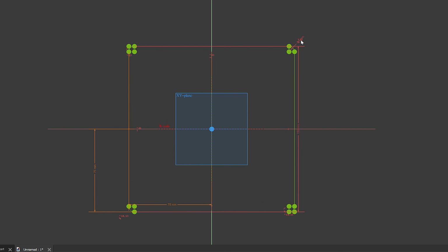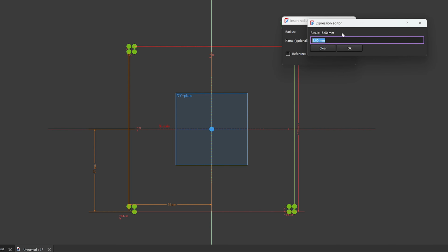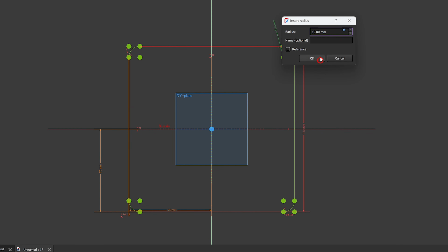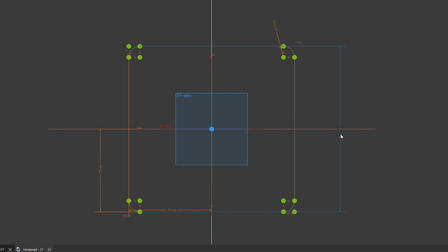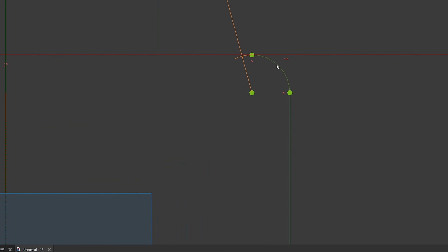We can also change the value of radius if we want to set up some kind of relation between the length and radius value. So let me actually do that. Here we have got 5. Instead of 5, I'm gonna write constraint dot rect length, and then I'm gonna say divided by 15, which translates the radius value to 10 at this size, which I think is kind of proportional. Now if I again go back and make this 126.8 and let's hit OK, you can see everything changed, and this value now became the following.